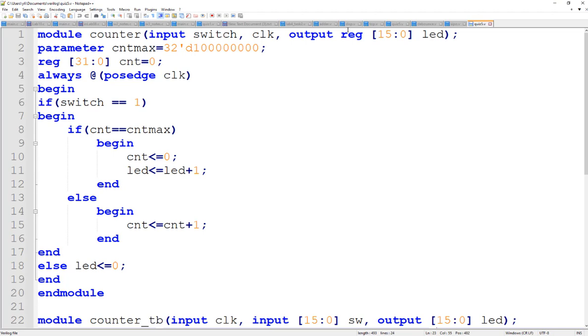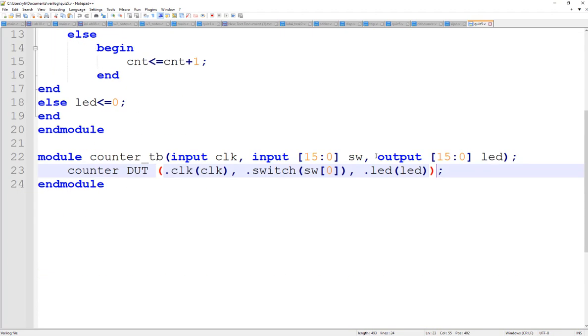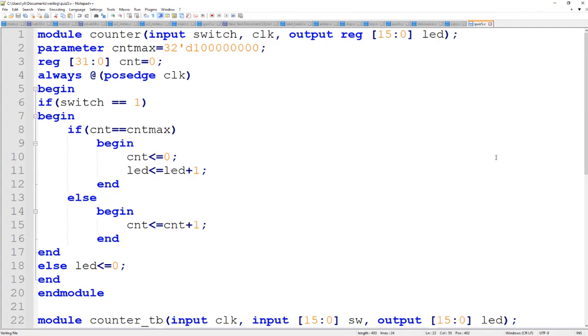But after you are able to latch that signal output and buffer it over there, all the following lines don't have to be buffered, because it's already latched or being controlled by the clock. So you can make a direct connection to the FPGA signal lines. You don't need two register types. Why would I do that? Like two latches, you control it twice. It's not necessary. You just need one stage of latches. Whenever the signal is over here, just clock it, and everything will be kicked out from that register array and eventually sent to the FPGA's signal lines. It's just a convention of the modeling. That's why we do it.